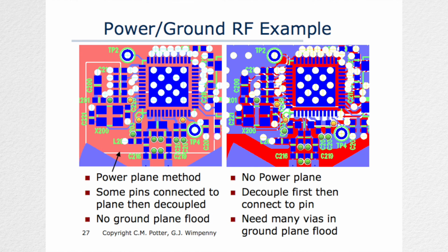The only one that wasn't quite right is this one over here, where you've still got a little track up here. What should have happened is that little track should have bridged across from the pad of this decoupling capacitor to get into those two pins. But no, that's the snapshot I happen to have. It was eventually picked up.